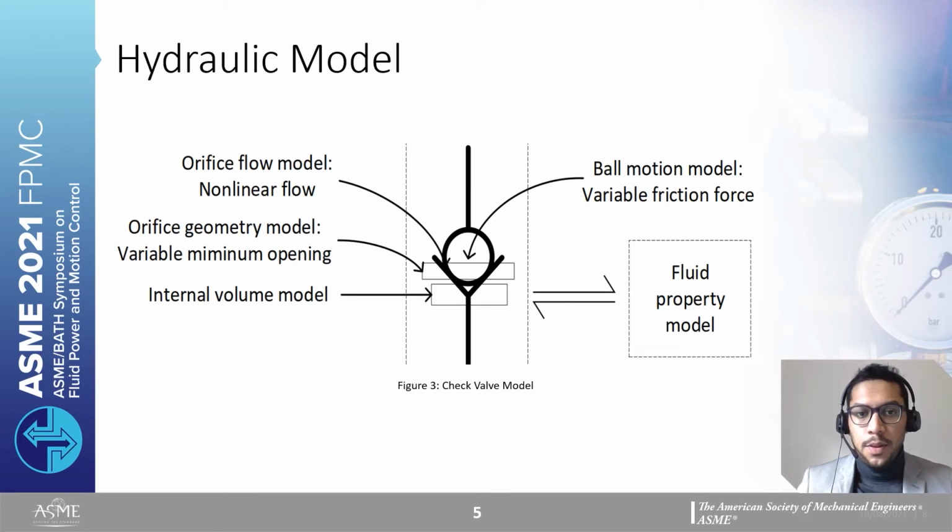The check valve model is shown here. It consists of the orifice flow model with nonlinear flow, orifice geometry model with variable minimum opening, internal volume model, ball motion model with variable friction force, and the fluid property model.